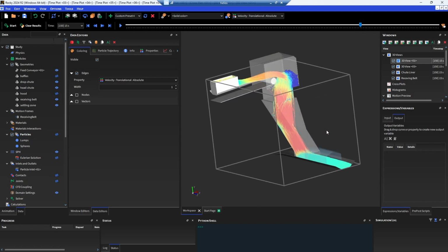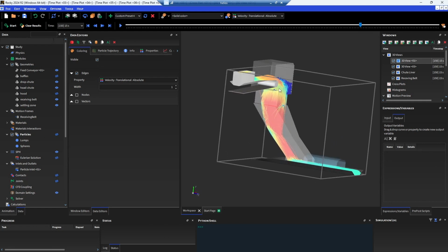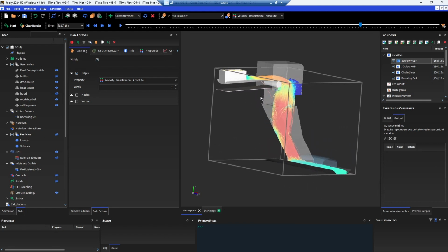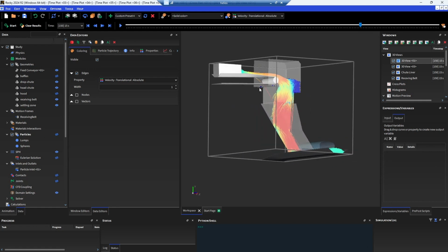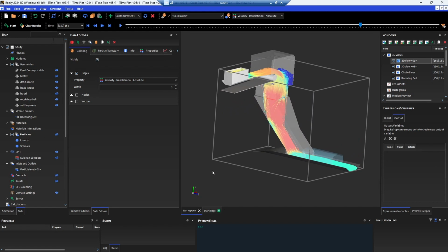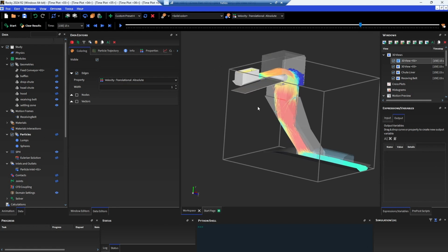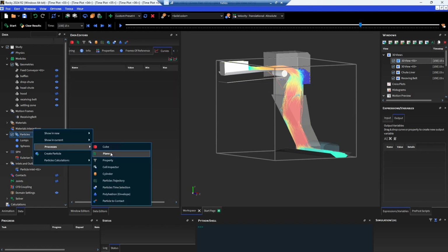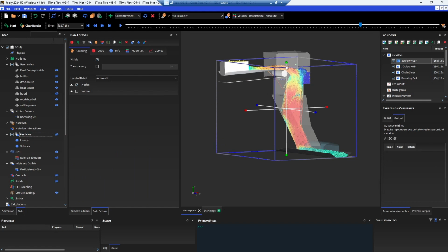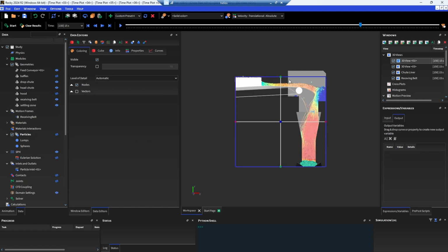Okay, so one of the other things we might want to look at is a material spillage perspective. So perhaps we want to make sure that if we have some personnel underneath this feed conveyor, we obviously don't want any material falling onto them that poses a safety hazard. And so what we can do is identify any material that had ever fallen off of this conveyor. And I'll do so firstly by identifying the region of my interest. And so I'll just size this manually through the GUI.